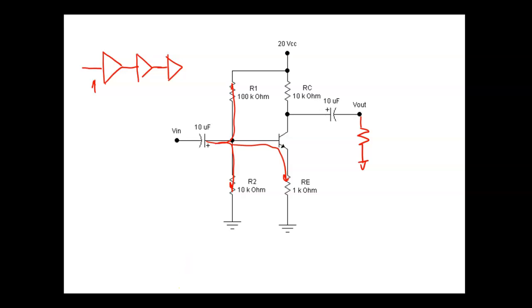So where are we at in the lab? What do we need to do next? RE prime was computed. Everybody okay there? Huh? RE prime was computed. Be like 57 ohms. 52 ohms? Okay. AV. So AV. Well, no, because we got it bypassed. So what happens is we came over here and added a load. So let's calculate it with a load.